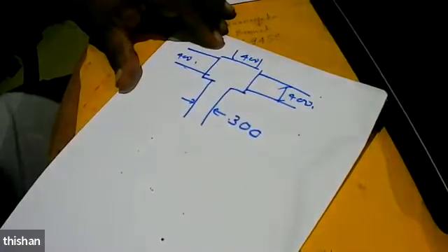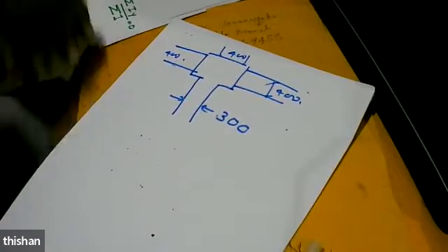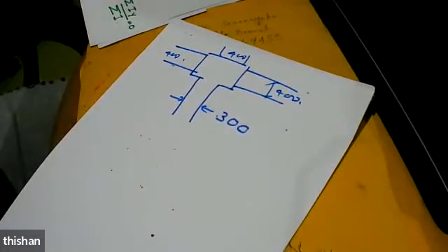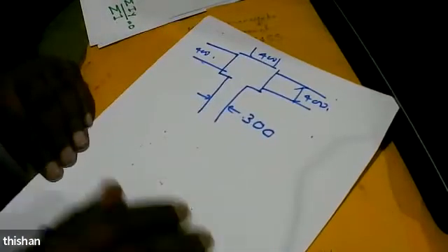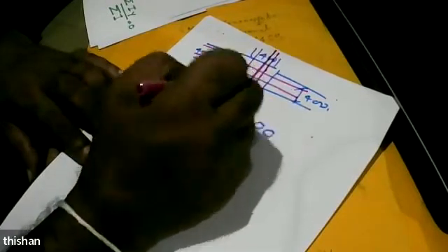then I would like to have a 500 column. Why? The beams coming here will be 400. So there will be 400. There will be 400. And if I have a 500 column instead of 400, what happens is, we get the reinforcement coming here. And this reinforcement goes straight. These can go in whatever direction, sometimes with some cranking, or what you do is you come with this beam and then have an additional reinforcement here. And then with all these, we can accommodate the corner reinforcement.